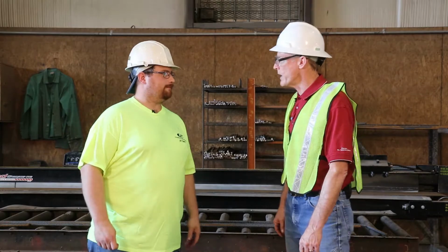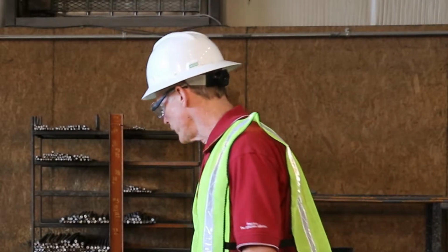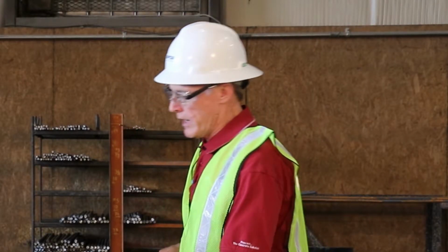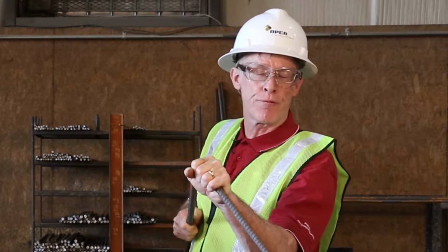That's great information, Michael. One thing I might mention, when you're bending the rebar, it's important to get the right radius. If you create too tight of a radius, it may crack the rebar and be no good for you. Additionally, if you have too tight of a radius with the concrete around it, when it's in tension, it may crush the reinforcing steel. So the radius is very important.